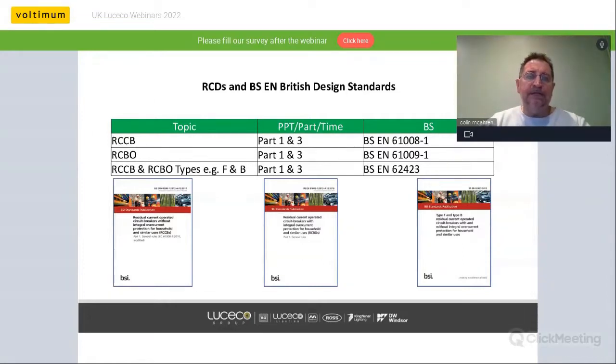There are also design standards within the BS EN 60947 series of standards for the devices. You're probably familiar with those as well, but I haven't put them up here because they're not generally employed in, say, residential or commercial applications where the units will predominantly have an adjustable trip setting and time functions, and as a general rule cannot be used for digital protection of final circuits.